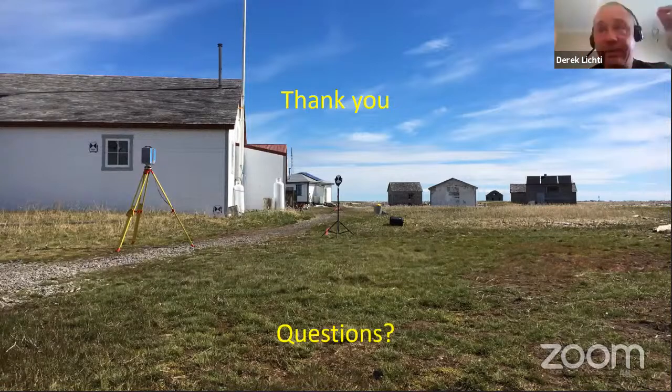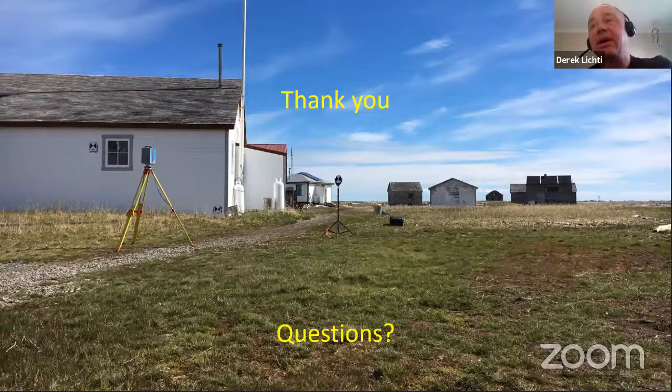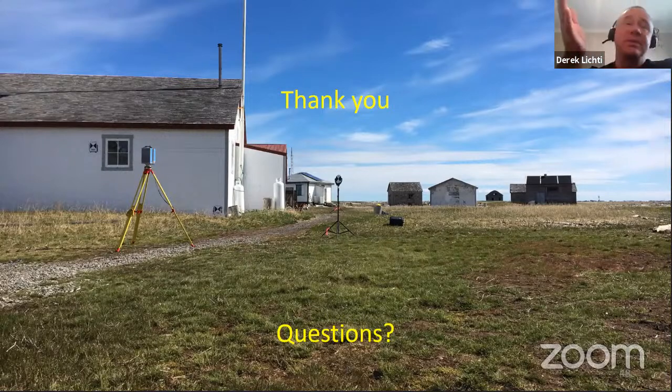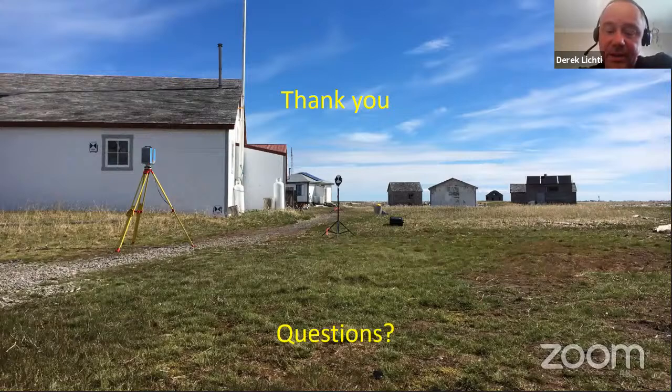Precision is a function of distance, and it's a function of incidence angle. We can boil it down to that. So we set thresholds for the maximum range at which we want to observe a particular wall, and the incidence angle at which we want to observe. Because above 65 degrees, for example, the precision of the distance measurements becomes very poor. So we limit the incidence angle in constructing the weighted greedy algorithm.